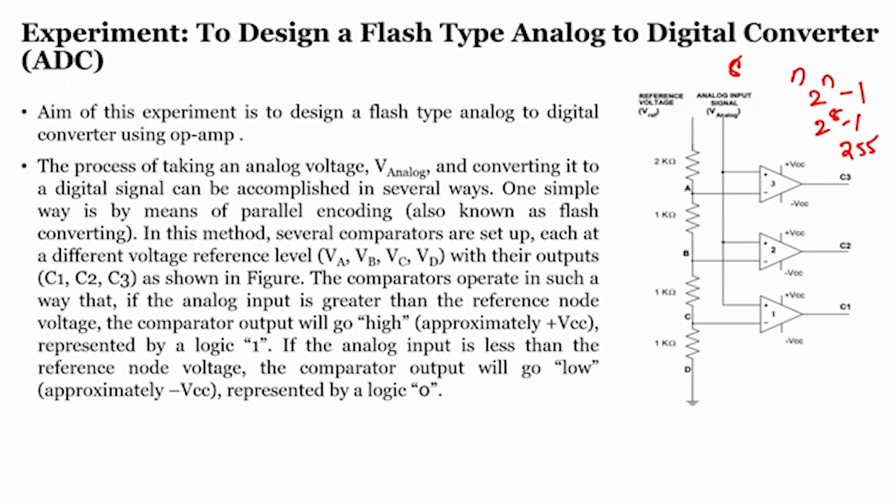If you imagine 255 op amps or 255 comparators, imagine the size of your board. Now if you see the microcontroller, it has onboard ADCs itself. If you observe the onboard ADCs as well as the microcontroller, the size will be almost equal to your 8-pin or 16-pin operational amplifier.